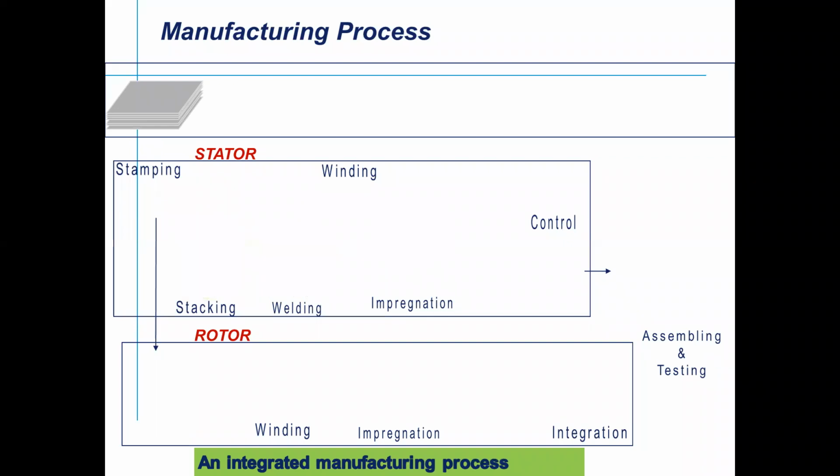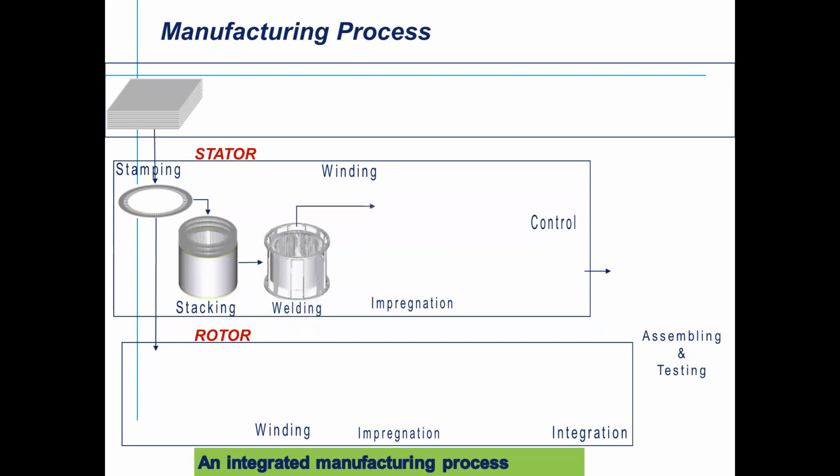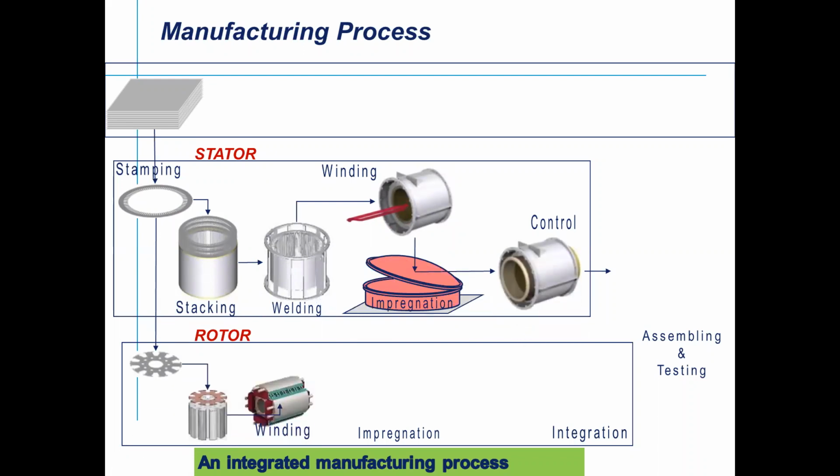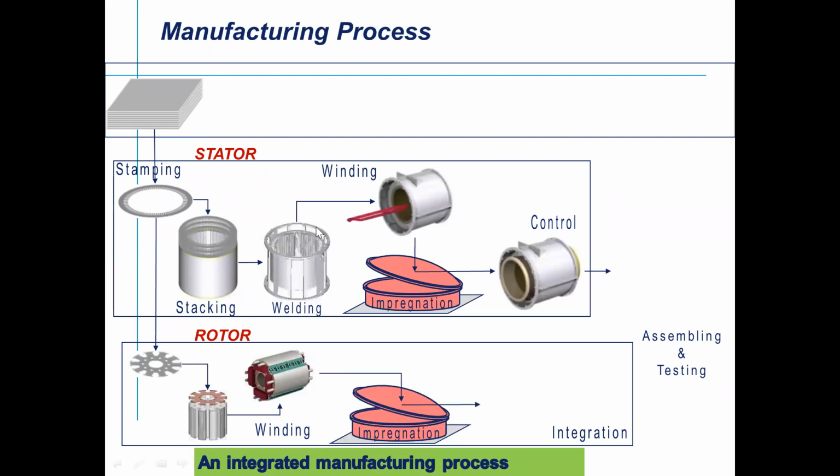Okay, fine, thank you. Coming to how the manufacturing process happens in the alternator, these are the stampings which will be used, and the stamping is made as a profile to the slot. Maybe 48 slots or 60 slots or 70, 82 are required based on the design. So the core stacking is done, and further to that, stator assembly, welding, winding, and after that, impregnation.